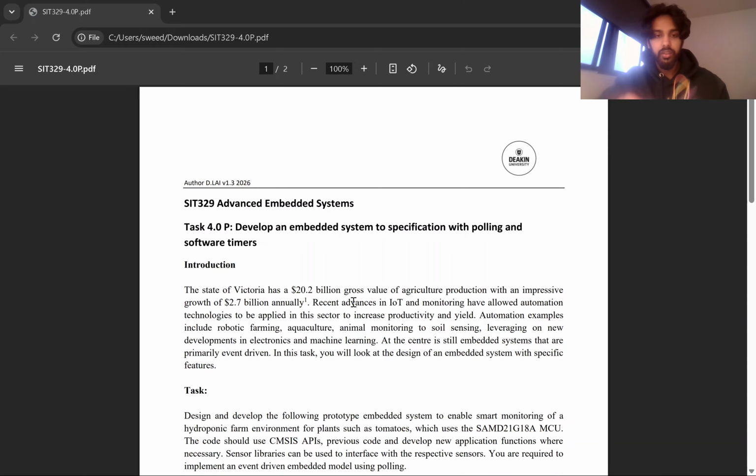So here you can see is the Nano 33 IoT and the whole circuit in which the DHT22 is connected. LED 1 is at D4, which corresponds to port A group PA07, and then we have LED 2, which corresponds to D5, which is PA05. And then comes the DHT22, which is on pin D2 of the Nano 33 IoT.